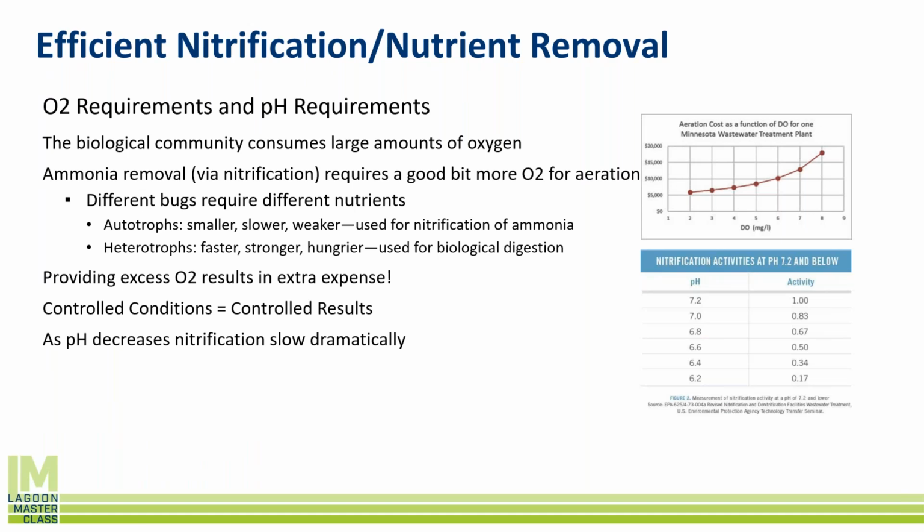If you look at a BOD test, typically on an influent 5-day BOD test, you're not going to pick up a lot of that nitrification. But if you go to a 10-day BOD test, you will see that full nitrification oxygen demand on a 10-day influent BOD test. But you can also just test that by testing the ammonia, and you can calculate it that way. So it's a lot easier way to do it.